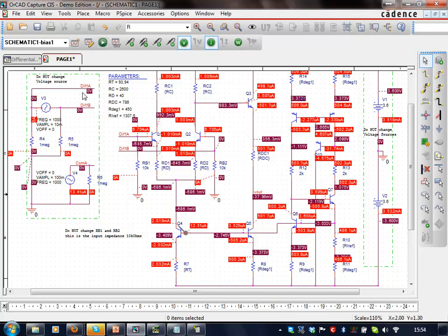So the differential 10 millivolt signal is going to come into this circuit, and we want to measure the common signal coming out from Vout down to ground. So differential signal in, common mode signal out, and we're going to look at what the gain is. The gain should be set to 20. Our differential gain ADM should be 40, and this should be set to 20, in effect, the way it's working.